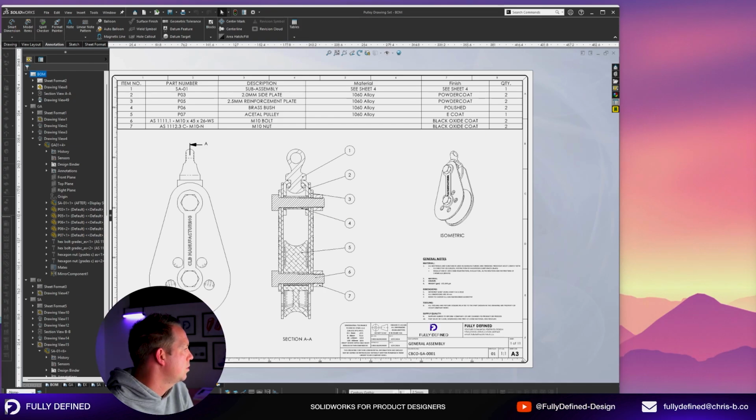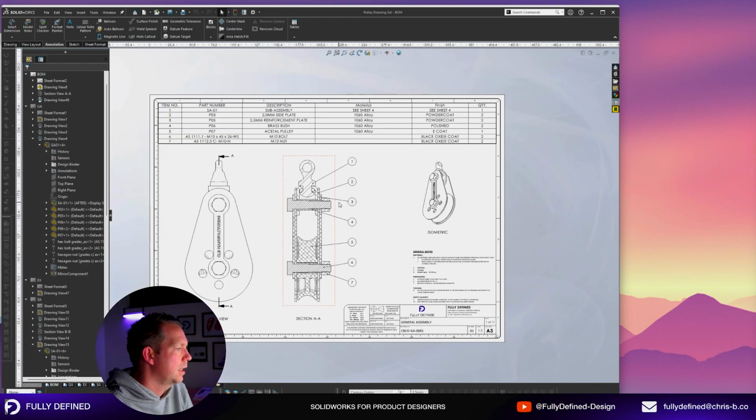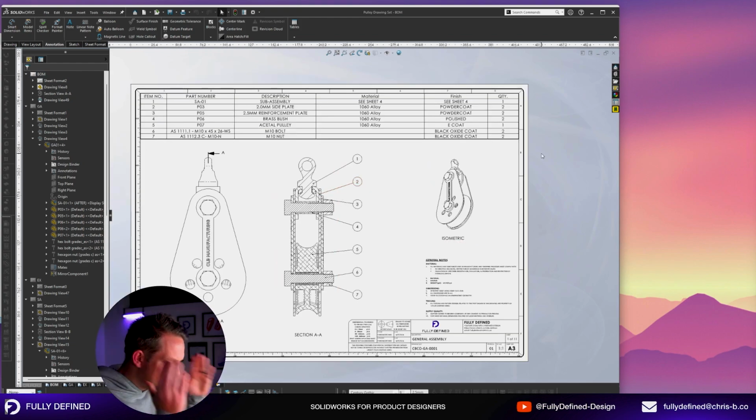The last step in this drawing is now going to be putting in our dimensions. Okay, so for dimensions, the key thing to think about here is what are your critical dimensions for parts to fit together? What are the critical dimensions for the viewer of the drawings to understand and to know? And where else might these drawings be used?